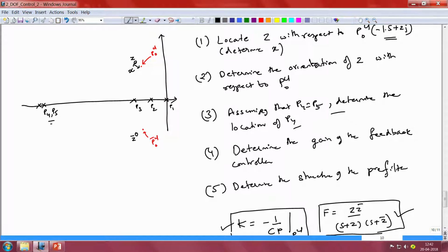So we saw that in order to undertake the analysis for the first step in the design, what we need to do is determine the shape of the curve or the area within which the closed loop pole would vary when the plant's parameters change.